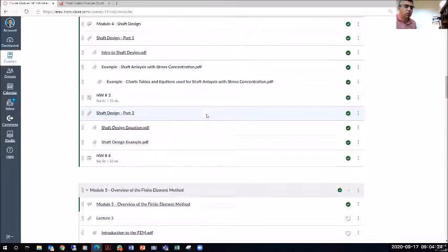And based on the dimensions that I'm going to choose for all the details of the shaft and the steps I'm going to come up with, I can make sure it meets a safety factor requirement by calculating the design factors at different sections. In order to do that, we simply take the Goodman criteria equation.